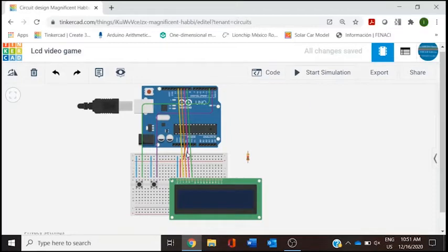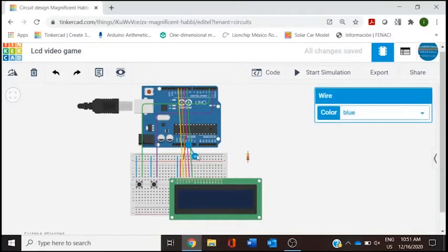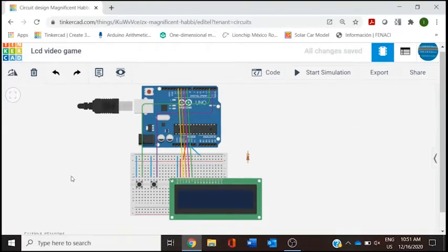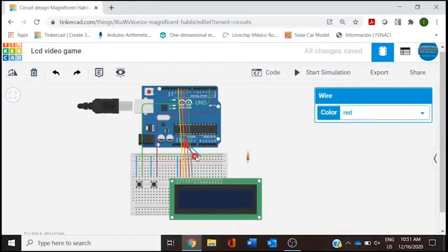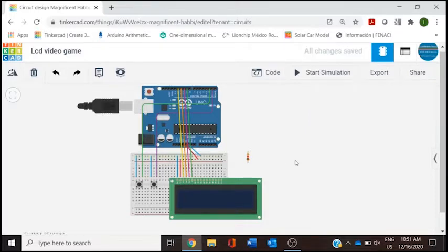So for seeing these cables better, we can actually change them to one of those rails, and that way we can see the connections better, like that. Now I'm gonna start from right to left because I need to test if the LCD has brightness. So if I start with the number 16, which is the cathode, this one indicates that the connection goes to ground.